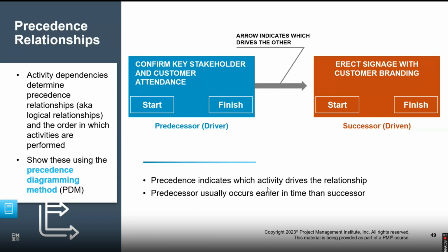Lag will be there. So if there's a delay in starting the next activity, there will be a lag. Maybe a sudden rain has delayed the plastering work or something. Yeah, like something has gone wrong. So if activity A completed and B did not start, that's going to be lag. Any difference is lag. It could be a risk because of which it has resulted in lag time. Probably it rained. We were ready, but it rained. That resulted in a lag time. So anything which delays it.